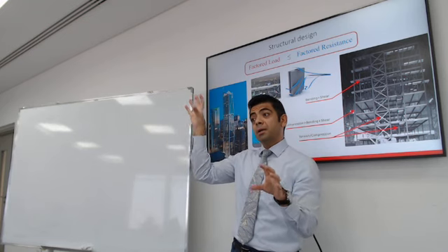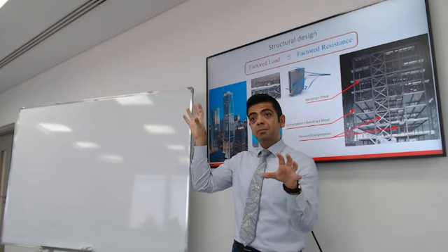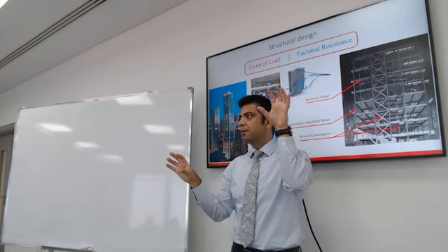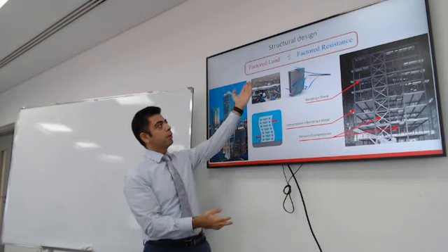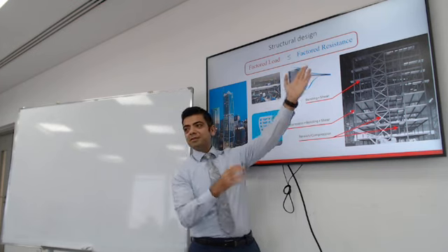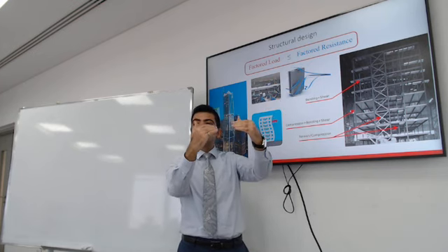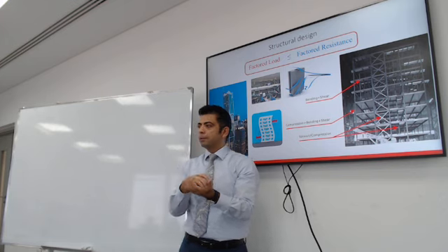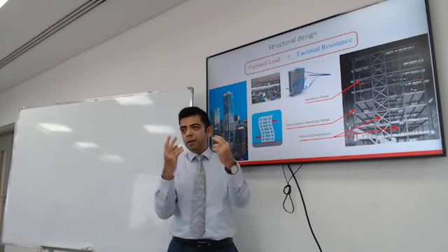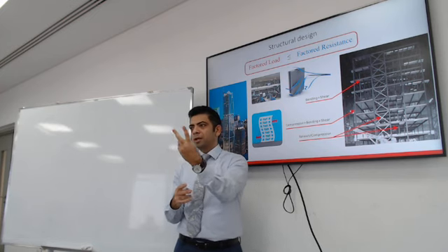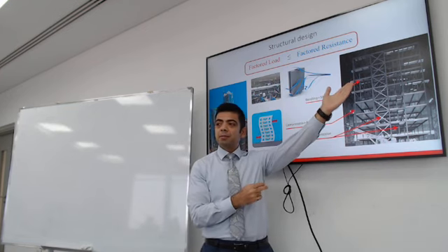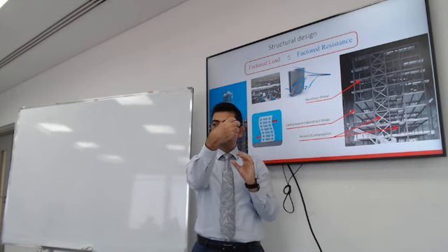You want the load to be bigger than the capacity of the beam, or you want the beam to be stronger than the loads on it? There you go. And that's the most important objective for design. You make sure that the resistance of the section is bigger than the applied load on it. So what we're going to be doing throughout the term is always figuring out two things. How much is the load on the beam, and how much is the capacity of the beam, and make sure that the capacity is bigger.